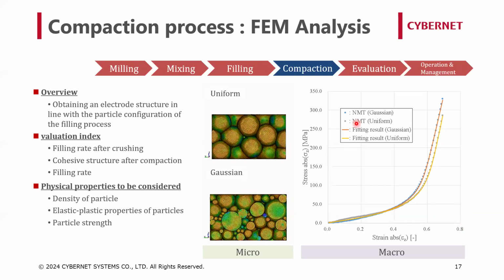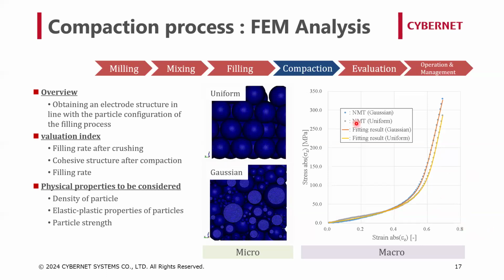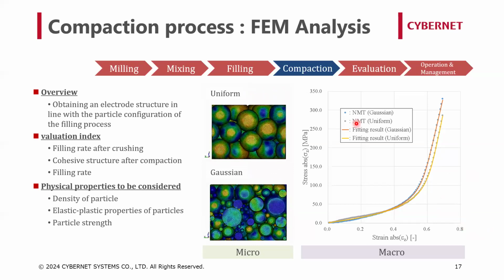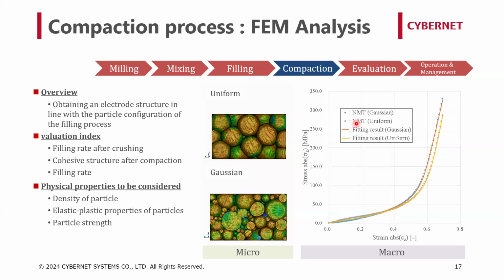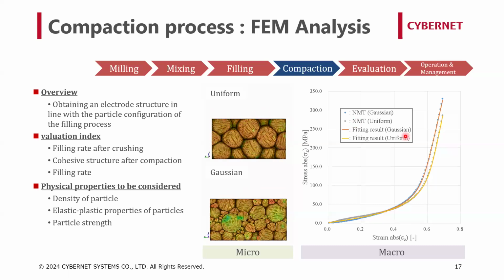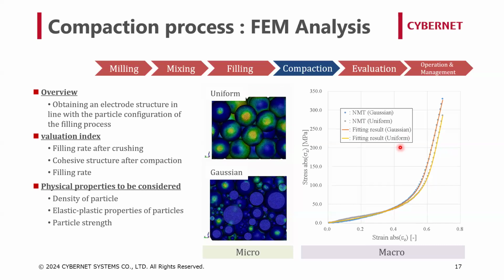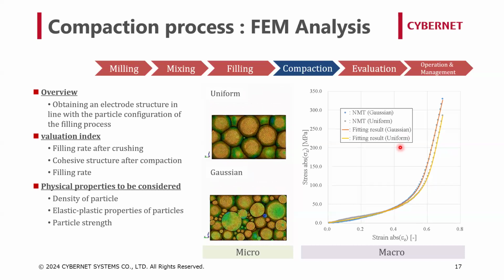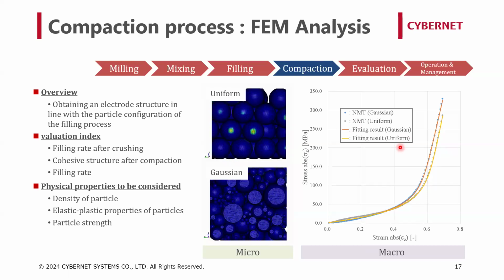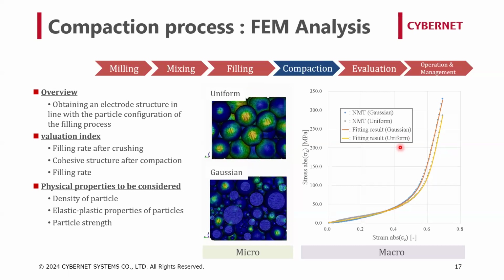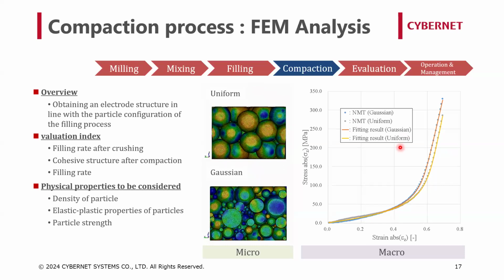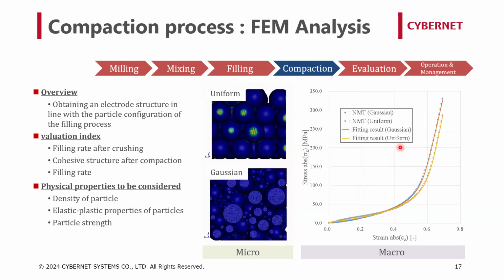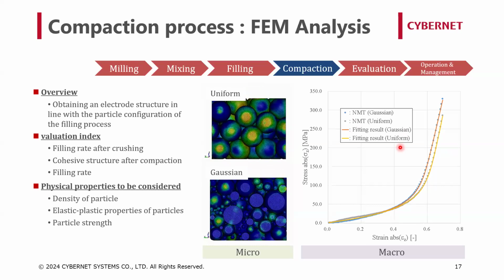Since the slope of this curve is almost equal to the stiffness, the material is very soft and flexible in the small compression ratio state. But the stiffness increases rapidly with increasing compression ratio. This corresponds to the transition of the material from the powder state to the solid state. This problem is solved by the explicit method using LS-DYNA. This method makes it possible to stably resolve the unstable stiffness behavior of the material in the powder state.